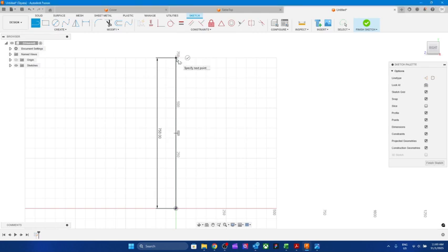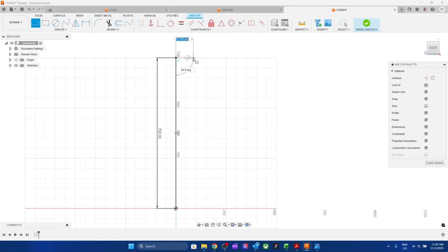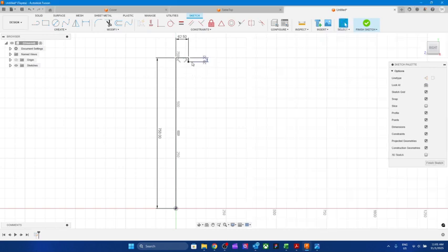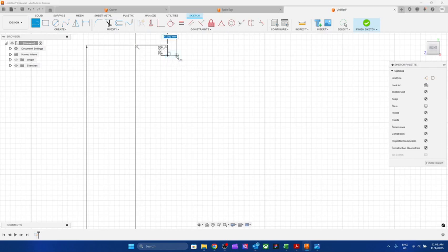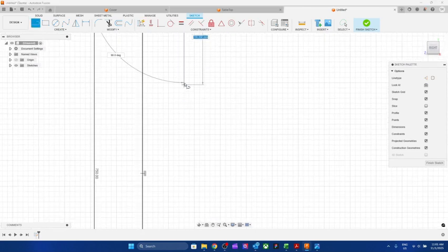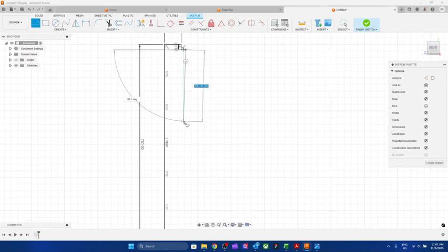and the size of the circle is, I said 125. So this is going to be 125 divided by 2, half of 125, yes. So 125 divided by 2, so I will select there, and further this is going to be 20 because that's the height I defined. And if you break the line, that's fine. So you can simply move this inwards and I can carry on drawing. So I hope you are imagining what I'm trying to do. I'm trying to create the leg. Let's create some sort of movement in the leg.